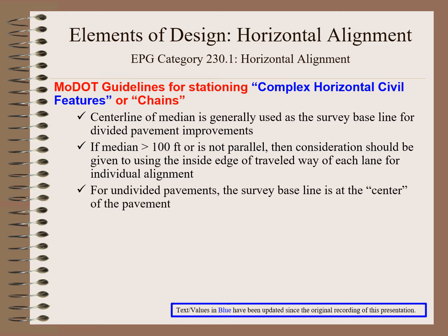For undivided pavements, the survey baseline is at the "center" of the pavement. And I use quotations for center because, as we discussed previously in section 1, the survey baseline is not necessarily in the center of the pavement. We use existing center lines whenever practical, so we need to make sure that we involve the survey party early on so that we can get those existing center lines staked.